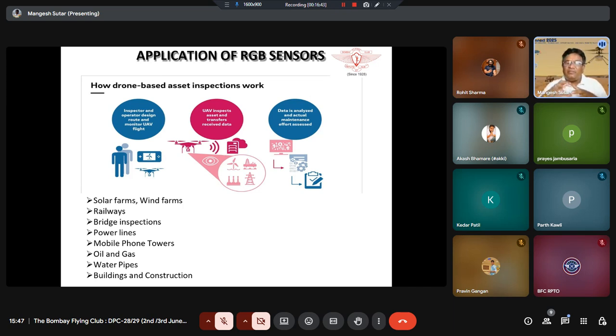Wherever we found something in our thermal analysis, we were able to identify the pipes where there was possibly more severe corrosion. So people took corrective actions, replaced those particular parts of the pipes, rectified those points, and saved a big problem in the near future. Possibly a similar kind of burst could have happened in the water pipelines.